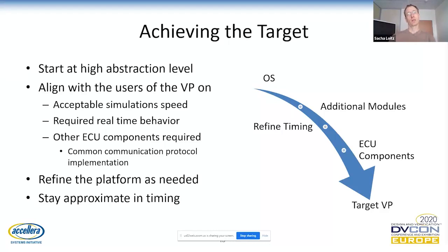Something that is on our side working very well here is, for example, a watchdog running between the microcontroller and another ASIC on the ECU. That is a very nice use case for a virtual platform, because you can debug that even far better in the virtual platform than on real silicon. But it also puts a lot of requirements into the area to get it running, because the watchdog has some real-time requirements, not hard, but they are there, that the watchdog needs to be served in a regular manner.